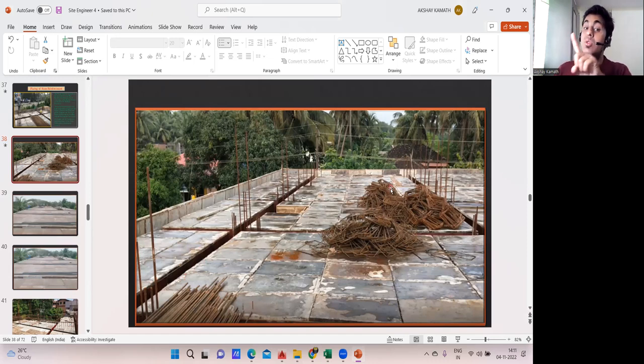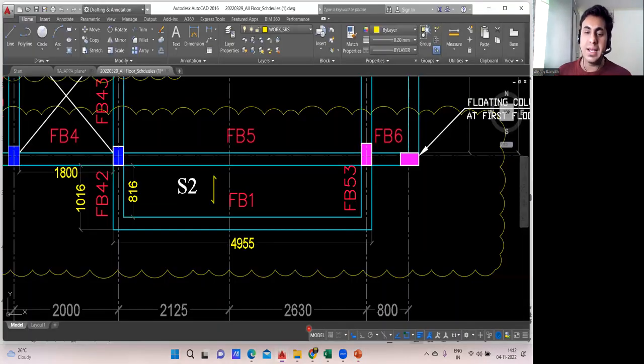Now coming to the outside shuttering. See, this is outside shuttering. Why is this height more and this height less? This height is more because it's outside shuttering and there's no slab on that side. So whatever 350 depth we had, we have put. This overall depth is 350, whereas here it is only 200 because on this side your slab is coming. But when you cast the slab, up to this top, everywhere it will be casted. Clear? Fine. With this understanding, I'll go forward.